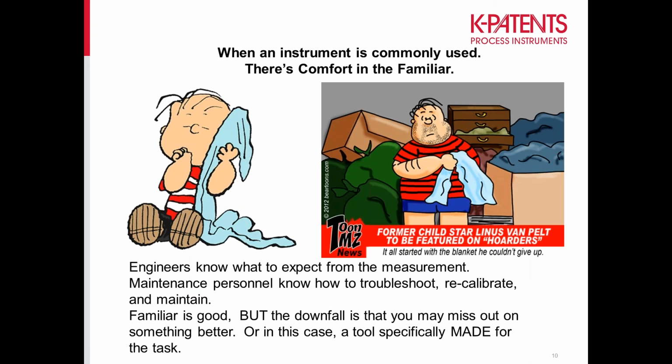So in theory, using density for concentration percentage, this is a graph of a concentration of a sucrose curve, and that would match a standard chemical table. So as the concentration goes up, the density goes up specifically. And when it's calibrated perfectly, the accuracy using density measurements or mass flow can reach plus or minus 0.1% by weight.